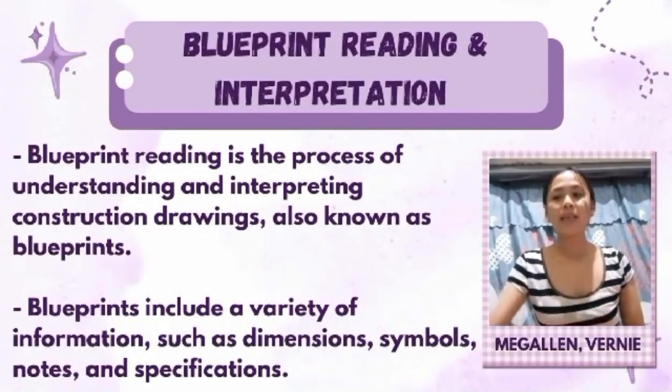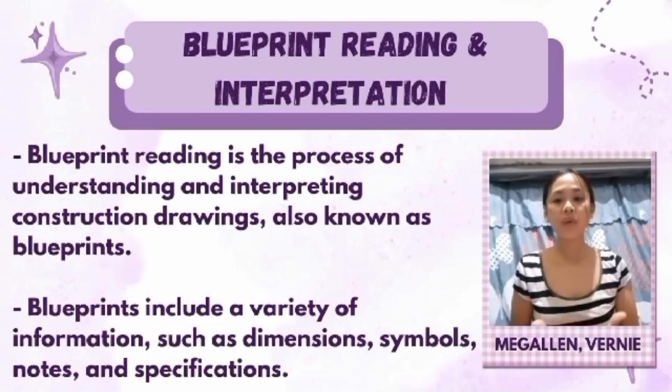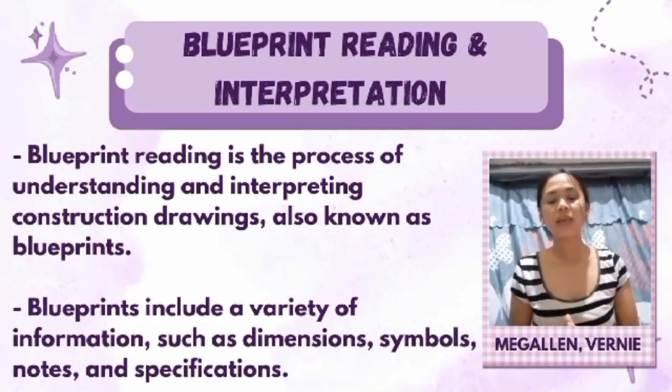So the topic is blueprint reading and interpretation. The first is blueprint reading, the process of understanding and interpreting construction drawings, also known as blueprints. This drawing shows the complete design of a project, including details and information, size and measurements, materials, and position of important parts.